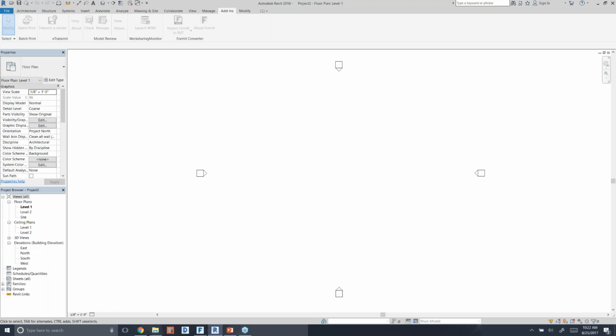And since those were just regular groups that I had made, the default category for them in Revit is going to be a mass category. And that's where they just imported. One other thing to point out, when I placed that initial cube, if you remember, I placed it right at the origin of the FormIt file where the red, blue, and green axes overlapped, the 0, 0, 0 point.